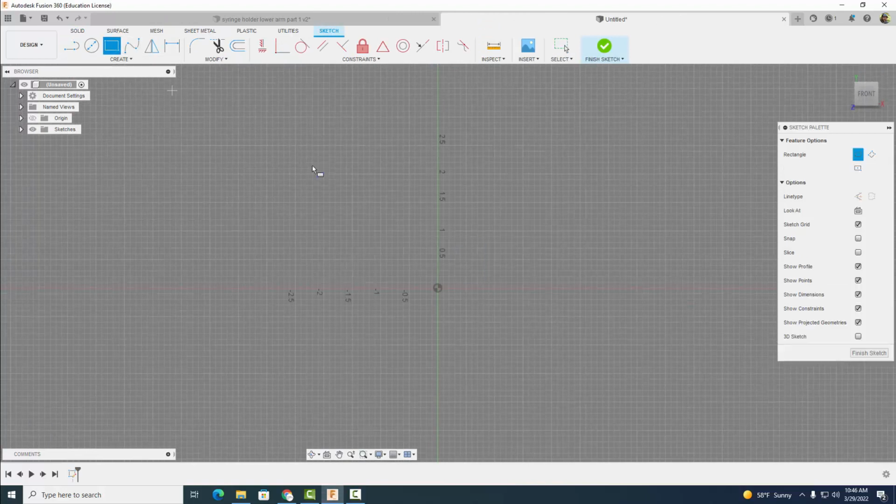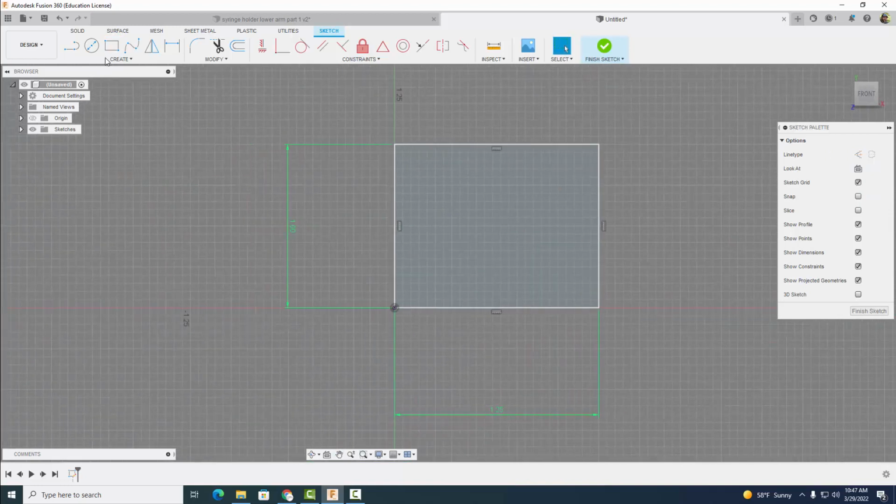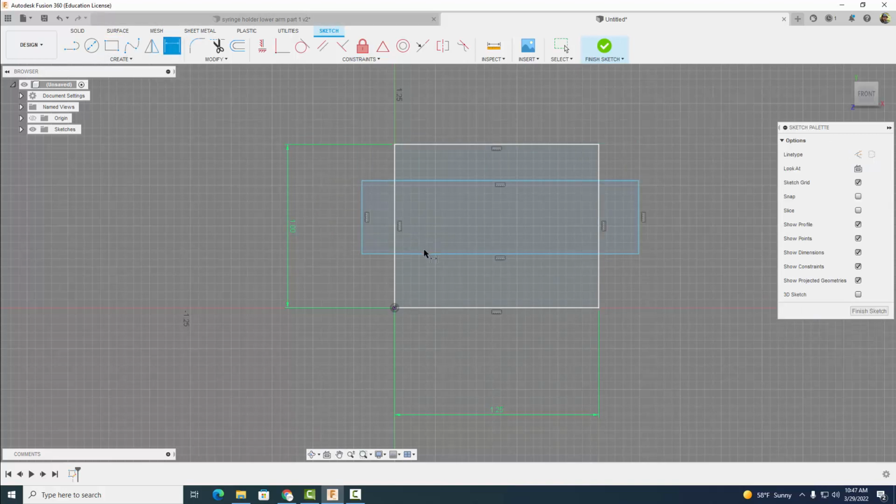First thing we're going to do, just like the other ones, is drag out a square, and we want this square to have the dimensions of 1, hit the tab button, by 1.25, enter. I'm going to zoom in, and we're going to drag out another square, something that kind of just looks like this. We're going to throw some dimensions on it from here to here, we want it to be 0.25. From here to here, that to be 0.125. And the same thing over here, 0.125.